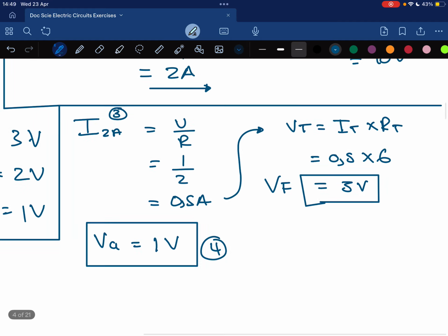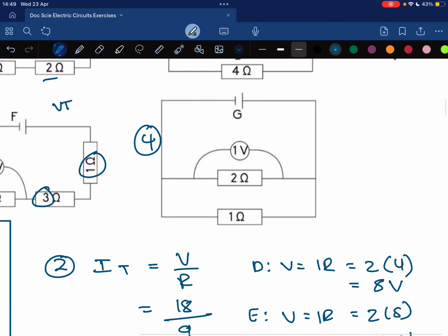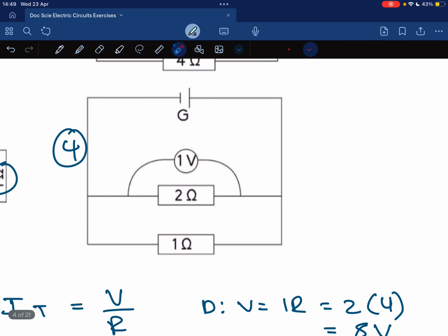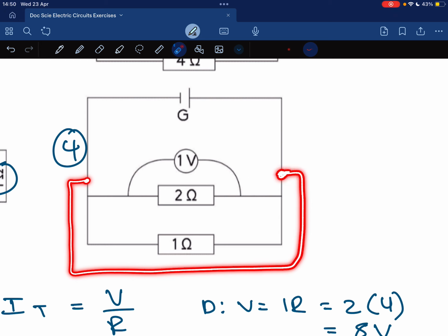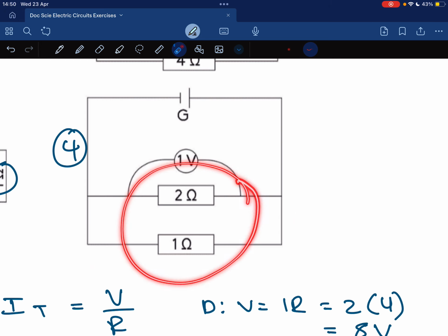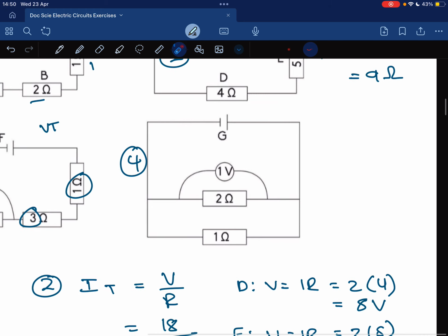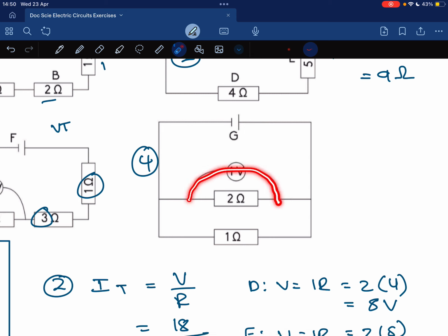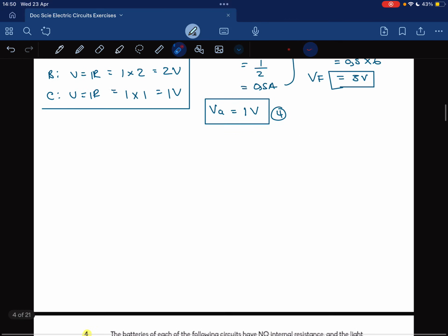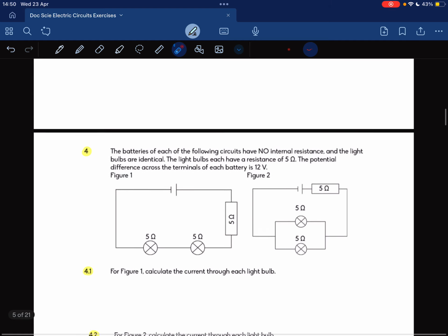The reason why that is the case is because the total voltage here is the voltage that's across, if I put a voltmeter here and took it all the way to this side, it's going to be equal to the total voltage because this is the total resistance. Now if there was a resistor here, which we'll do in the combination circuit, that's a different story. But here the voltage is equal here, which is equal here, which is equal over the whole thing, which is the total. Okay, so just make sure you think about that.